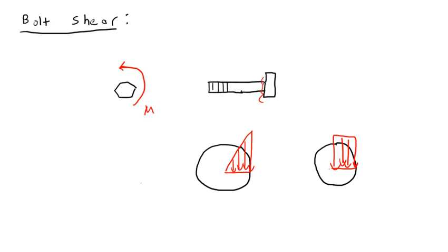So yes, you could use an enormous cheater bar, but you would want to be very careful to apply force very slowly. So apply a small force and then gradually ramp it up until you're at the limit of your strength. You wouldn't want to just instantaneously shove down on that thing with as much strength as you have, because it doesn't have time to transfer the load and release the moment, and it will just break off like that. Does that kind of make sense? It's a time delay thing, actually.